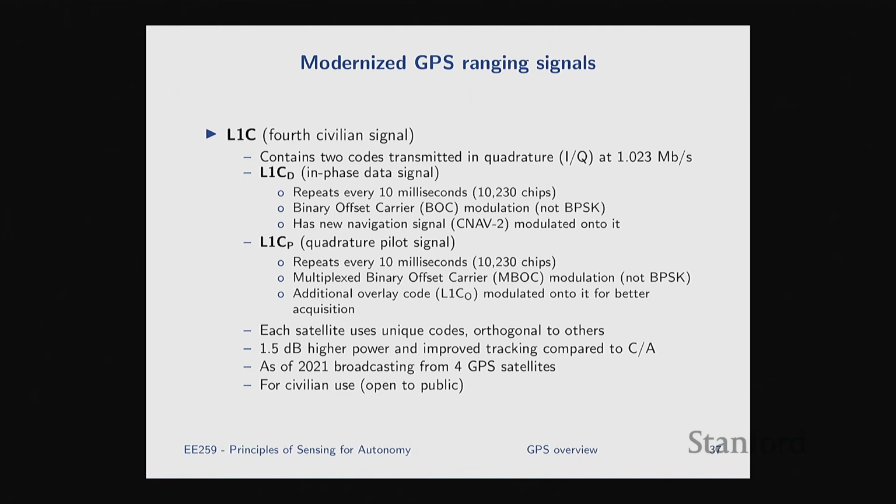And again, you see these are slight variations they're doing on these codes. Each adds a benefit in a certain use case. Some are good for low SNR cases. Some have better accuracy for ranging. The BOC is more energy efficient. It's just these slight variations that they're doing to different modern codes, to ensure more availability and more universality across use cases, locations, and devices. That's basically the idea. But if you abstract out all the little details of what the code is called and what exact modulation is used, and go down to the core mathematical principle of how these operate, as we'll see, they're exactly the same, identical. So we will just look at the CA code, because everything else is identical to that.